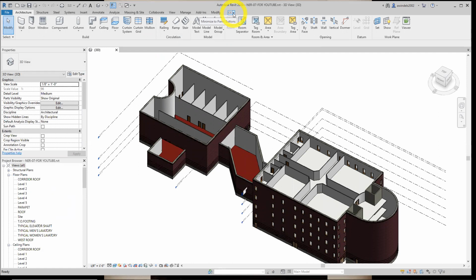And like I said, we have a lot of different types of roofs. We're going to do a flat roof with some drainage, mostly looking flat though, a gable roof with two open-ended sides that are slope at the ends. The ends are left open. That's a gable roof. A hip roof, which with all sides are sloped. And we're going to have mostly a gable roof in the middle here with some hip in the middle. A hip roof would be kind of like on a ranch style house, something that has slopes going to all sides, hips and valleys. And then we're going to try an extruded roof with a unique shape. So let's start with flat roofs by footprint.